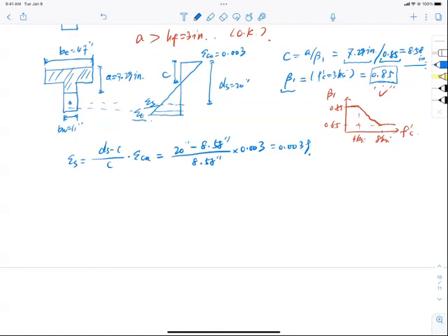Aubrey, should I be happy with it? It's in between 0.002 and 0.005, so it's in the transition zone, but still under-reinforced. Like it's okay, but not great. Exactly. Thank you so much for the information, Aubrey. That's absolutely correct. So it is half-half. I'm half happy because it yielded. So yielded, sure, but it's not tension controlled.